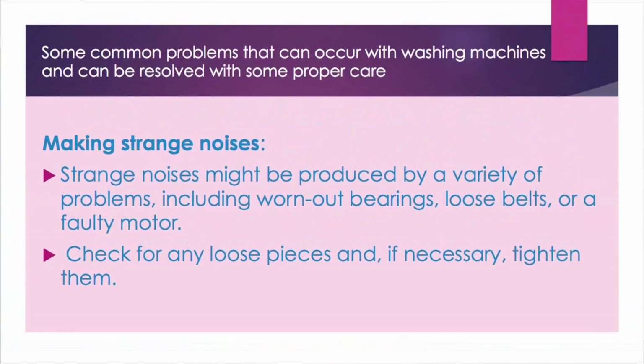The next important problem that can be seen is the machine making strange noises. Strange noise might be produced by a variety of problems, including worn out bearings, loose belts, or a faulty motor. Check for any loose pieces and if necessary, tighten them. If this doesn't address the problem, then in that case you have to contact an authorized service center for repairing the machine.